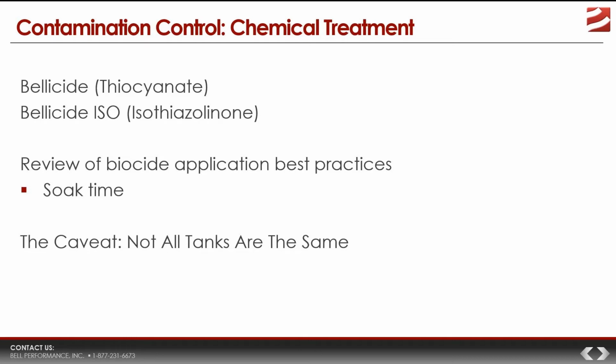Even though our biocides, even though thiocyanate and isothiazolone chemistries are broad spectrum, you also have to recognize that not all microbes respond exactly the same to them, too. This is why, and we're tying this all together, it's important to do things like condition monitoring. If you're not doing condition monitoring, if you don't have a tool like ATP testing to enable you to do that, then many times you are only guessing at whether you have solved the problem.